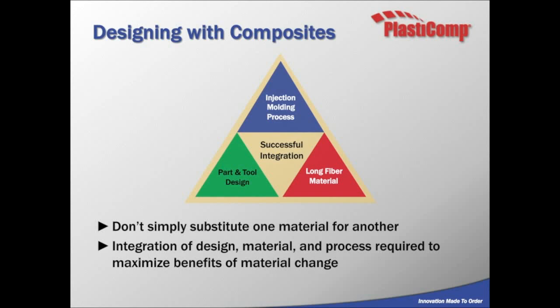And then you want to think about the material itself, like the long fiber. Which type of fiber do you want to deal with? Glass, carbon? Do you need long fiber? Does the part need to be fiber reinforced at all? What kind of resin matrix will this be working with?